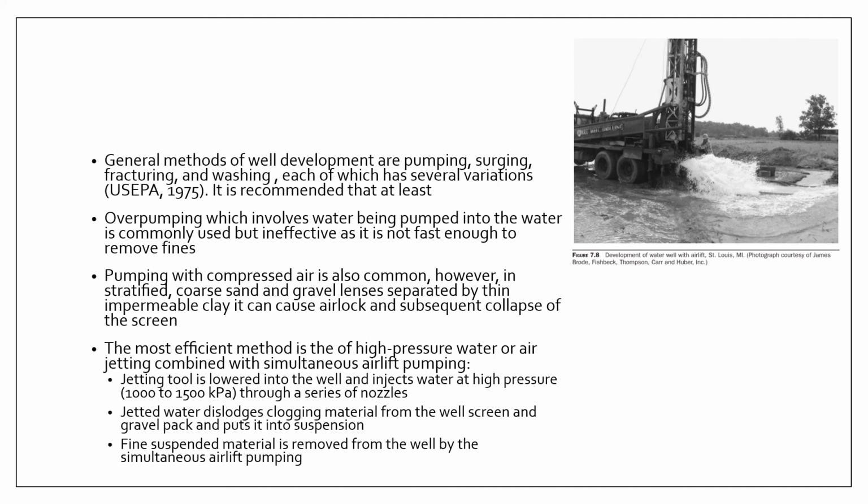Now, for the methods used in well development, you have pumping, surging, fracturing, and washing. And note that there is also a common method which is called overpumping, and this involves pumping water into the well. Although the problem with overpumping is that it's not fast enough to completely remove the fines in your well. So overpumping is a common method, but it's not the most effective method to use.